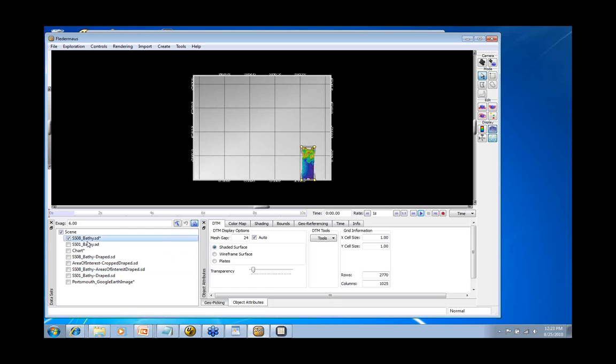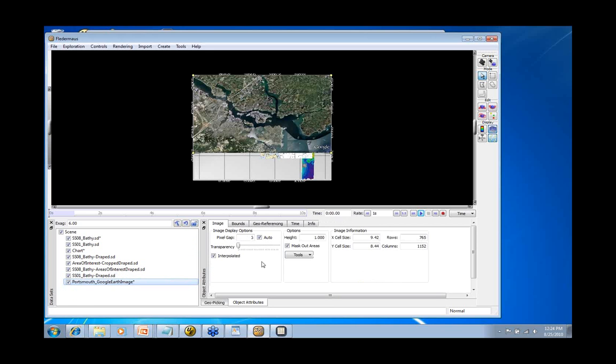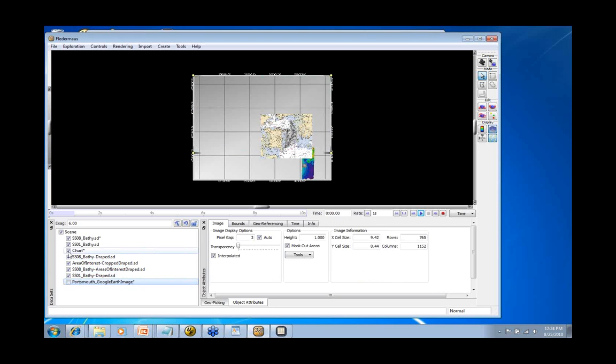You would use the map sheet if you had a lot of data and you really wanted a geotiff of the whole thing. So if I were going to do a geotiff, I might turn on every little thing that I have here. Okay, I'm going to turn off this because that's a bit noisy. So you would turn on whatever you want to be in your final geotiff map. Again, no matter what, if you could see it or not, it's going to be the same extent as this gray box, and it will have whatever turned on that you choose to turn on.